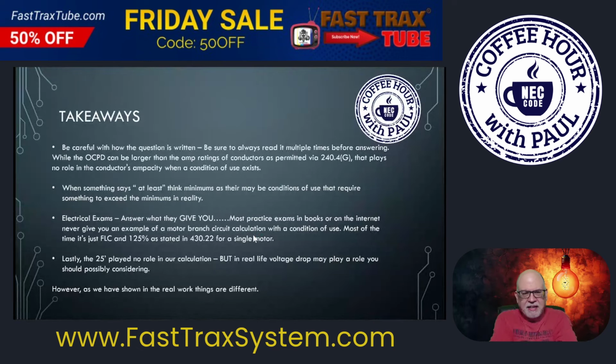So some takeaways from today's lesson. Make sure you always read the question. Remember that small conductor rules don't apply when it comes to motors. Remember, when something says at least, that's a minimum. So when it comes to those motor branch circuits, it says it has to be at least 125% of the FLC. At least, remember that. In most electrical exams, they're probably not going to have a condition of use like more than 3 current carrying conductors or an elevated ambient, but you know how to do it now, so you'll be prepared for that if you have to.